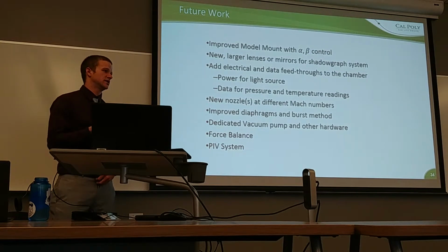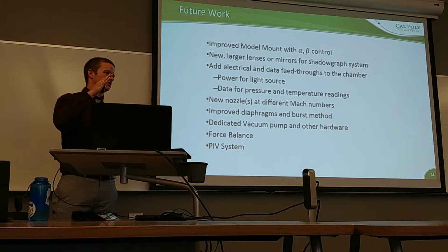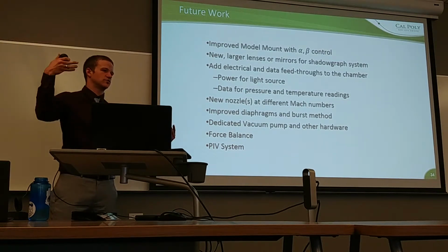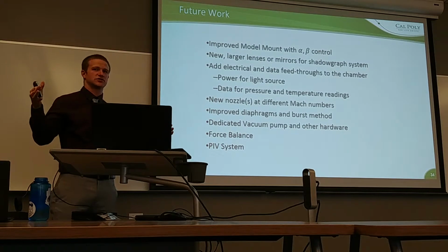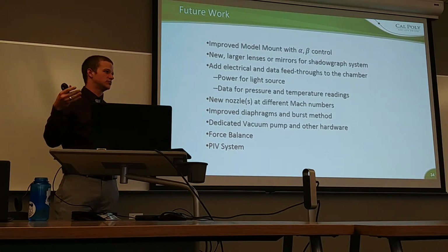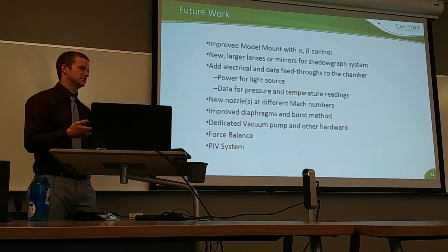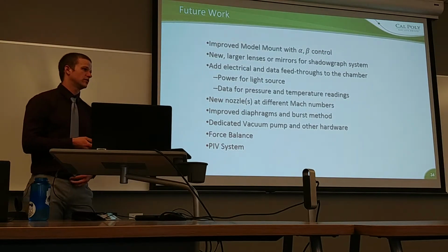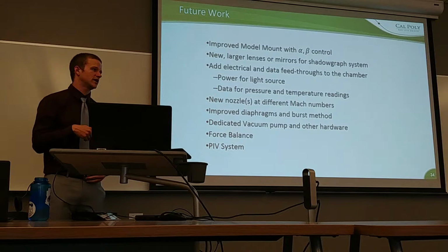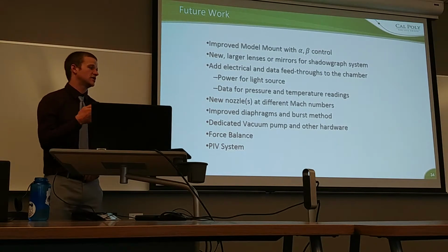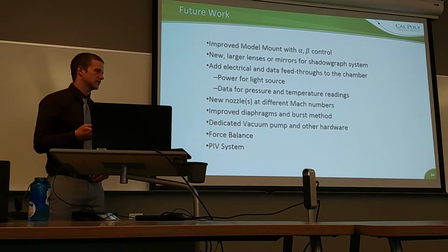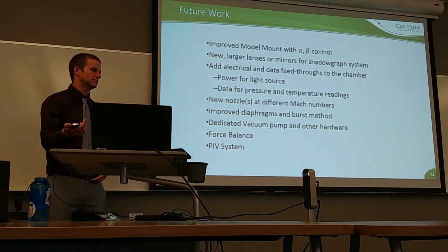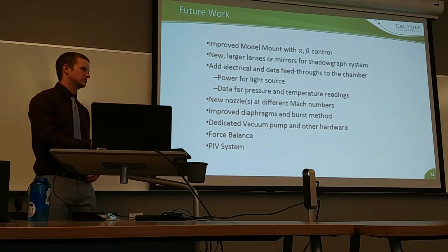What can happen though is as the pressure rises, the pressure pushing in on the outside, radially into the side of the nozzle, which is just the stagnant pressure of the chamber, exceeds the pressure of the flow. Then it starts to be able to push into the nozzle, and that impacts what Mach number is reached because it effectively reduces the exit diameter of the nozzle and truncates it down. So up until the point where the flow shifts from being underexpanded, not counting the propagating normal shock, the flow isn't able to be impacted by the pressure of the chamber. But once that point is reached, then it does.